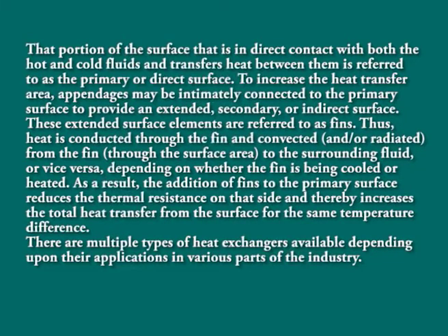Thus, heat is conducted through the fin and convected from the fin through the surface area to the surrounding fluid, or vice versa, depending on whether the fin is being cooled or heated. As a result, the addition of fins to the primary surface reduces the thermal resistance on that side and thereby increases the total heat transfer from the surface for the same temperature difference.